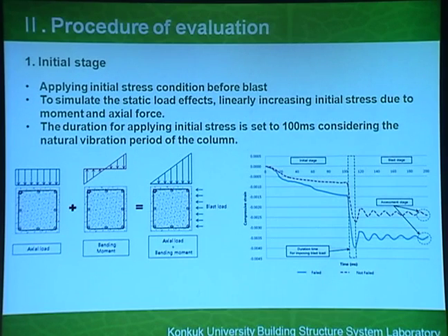As I said, we use AutoDyn to simulate blast effect, but AutoDyn is basically a nonlinear dynamic program, so it lacks static features. So we have to come up with some way to apply a static load with AutoDyn.